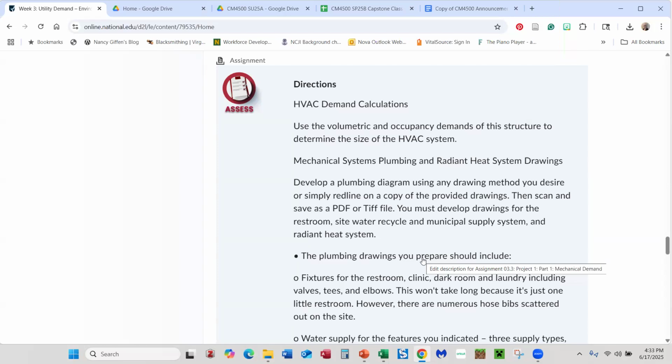And then take your sanitary line out. Keep it at least 6 feet from your supply as it heads out. And you're going to say sanitary sewer in the street. So the sewer and the water have to be 6 feet apart minimum, when they're coming in the site.